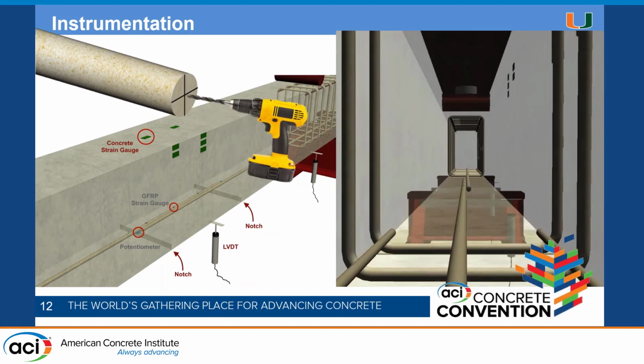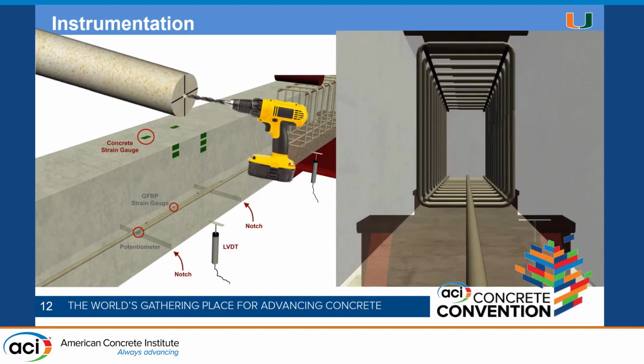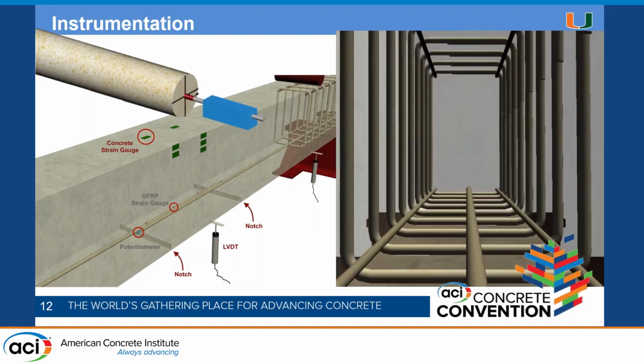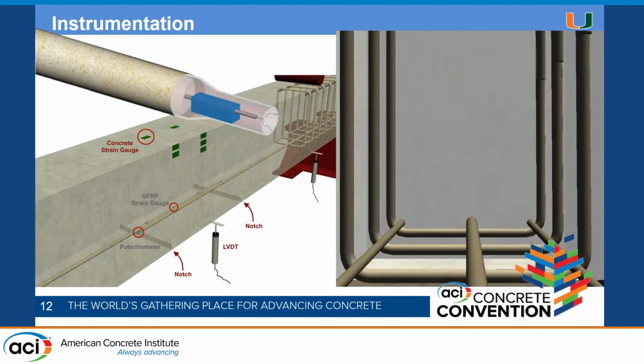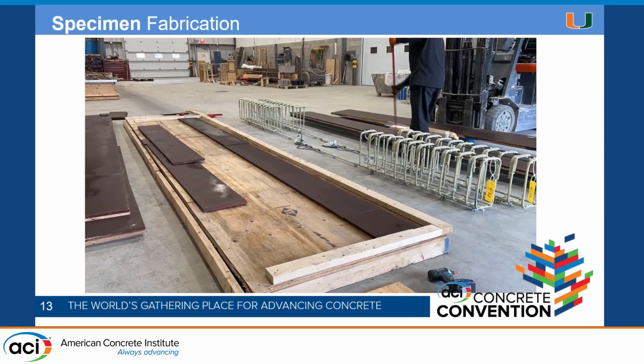As I mentioned, we installed some small potentiometers, so we made a hole on the rebar, and we installed a small potentiometer there. Of course, we covered that potentiometer to avoid any damage when pouring the concrete.